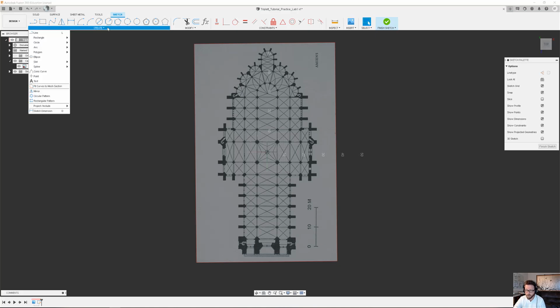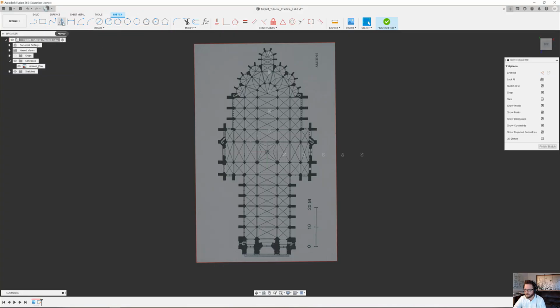I can also go down. I'm going to really quickly do this. I use the mirror tool quite a lot, so I'm going to right click on this and I'm going to say pin to shortcuts, and it should be pinned to the toolbar. Oh yeah, there it is already anyway, so that's okay. So that's on the toolbar, but I'm just going to start with a line. So I'm going to click on line, and right down here down the middle, it doesn't matter where you start, I'm just going to draw a line from here to here.